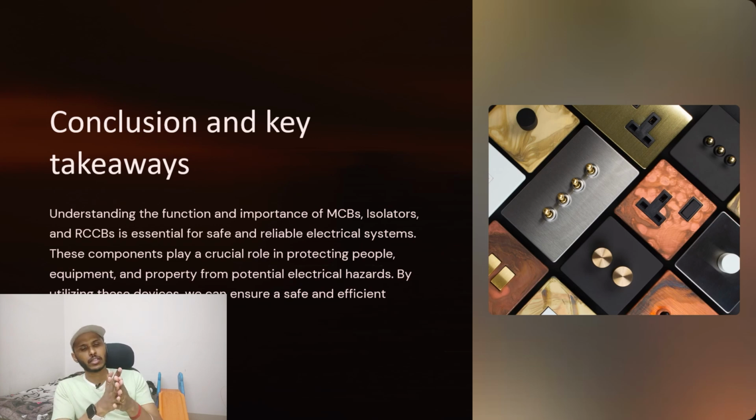If you don't have an RCCB, then you are prone to electric shocks from leakage currents. If you don't have an MCB, you have a greater chance of your equipment being damaged, and you will cause many other things like equipment damage, short circuits and cable damage. If you want to ensure protection against that, then you have to keep the MCB.